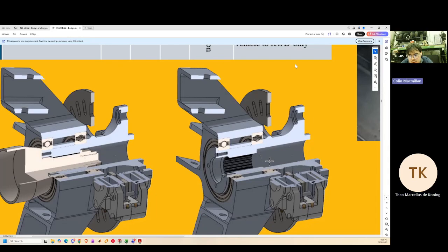Why would that need to change your track width? I think it had to do with packaging the caliper in with the rotor. It was just too close to the hub, but you can see the clearance here. We needed to space that out a little bit more to be able to fit the caliper in here.